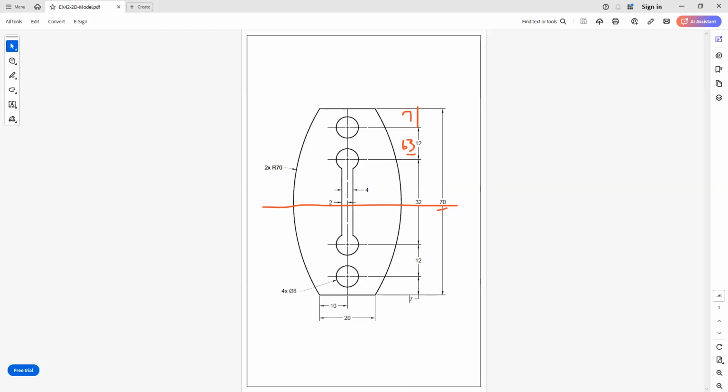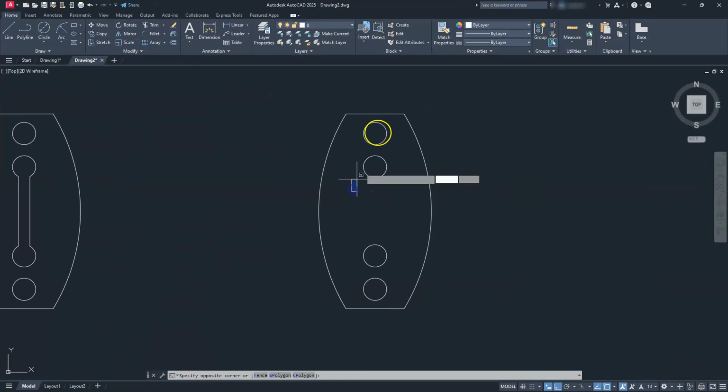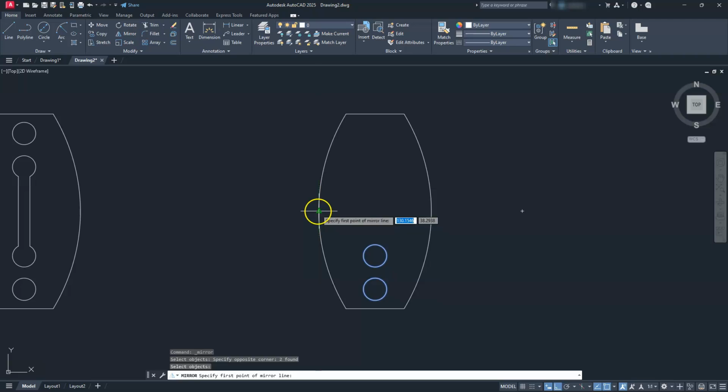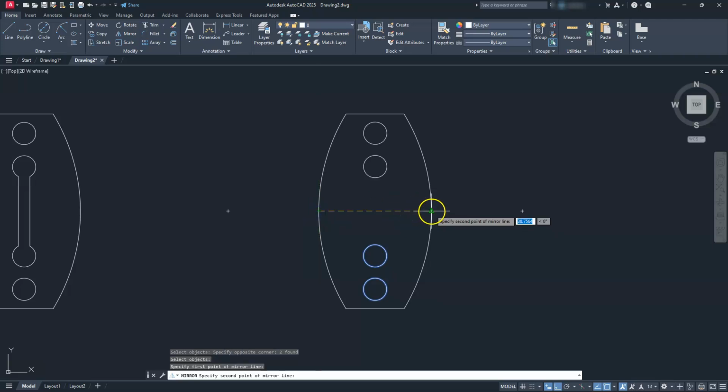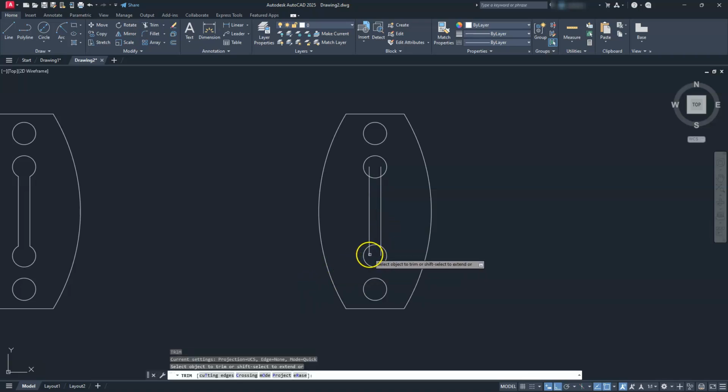All right, let's switch back to AutoCAD now. Okay, so what I was trying to tell you lastly is that if I got rid of those two, I can get away with also mirroring these two circles from that quadrant or midpoint going right across to here. All right, exact same thing we did on the other one. It'll just be simply drawing a line from here to here, offset a distance of 2, 1 to each side. Let's go ahead and get rid of that middle one there, and then we're going to go ahead and trim. Now I'm just using the shortcut since I already created this shape for you in the other example there.